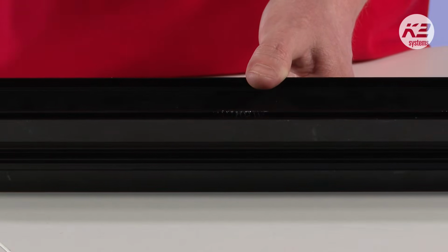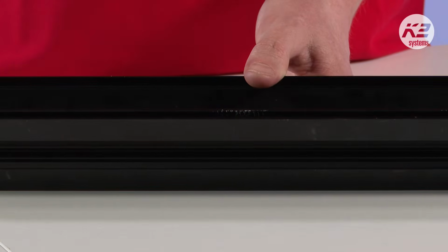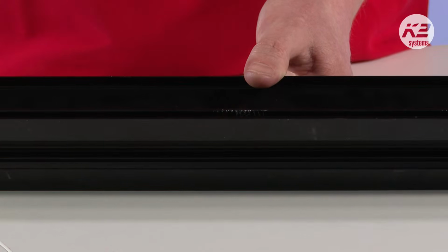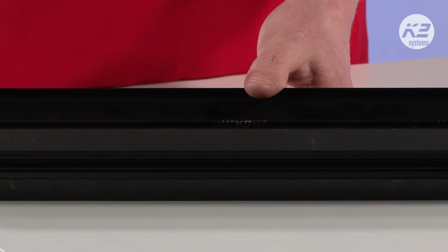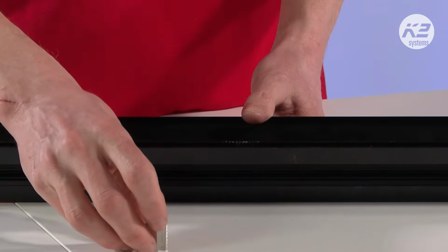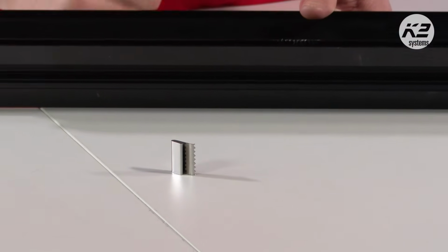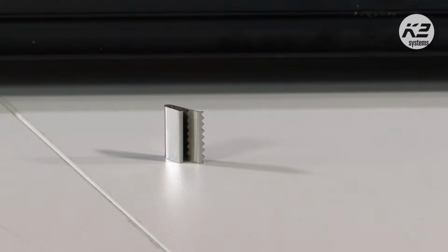If you have the need, which often you do, and we always recommend you do, earth your panel frames as well, unless it specifically says you don't have to. You can do that with this TerraGriff product. We haven't done it on the installation because once you get this in with the panel, it makes it quite a bit more difficult to get back out.